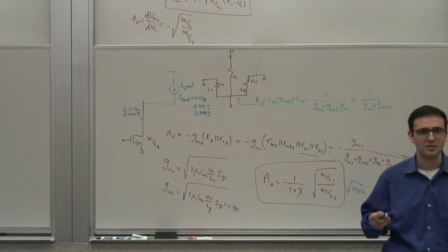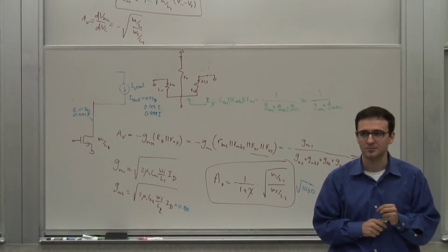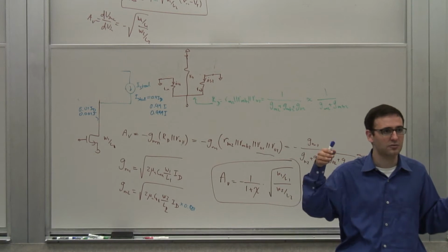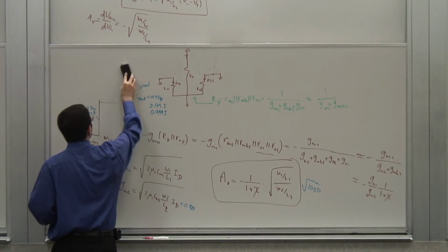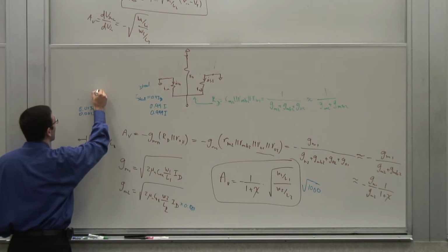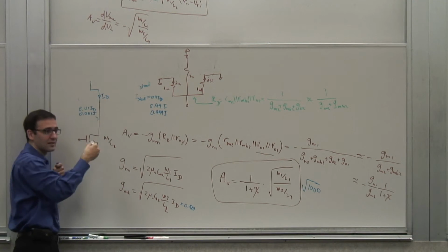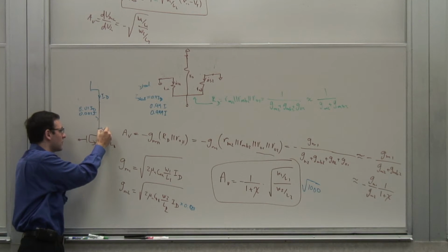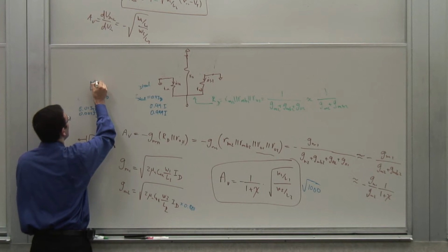What gives me constant current? Well, a well-defined non-zero current with a high output impedance. A transistor. The drain of a transistor is relatively high impedance, right? Looking into the drain of a transistor, you see RO. So what if I just replace this with a transistor, but I need a drain here, right? So this needs to be the drain. Now, the DC current needs to flow out of the drain, so it can't be an NMOS, obviously, because in an NMOS the current flows into the drain. It sinks current, it doesn't source current. But a PMOS is the exact opposite of it. So if I use a PFET,